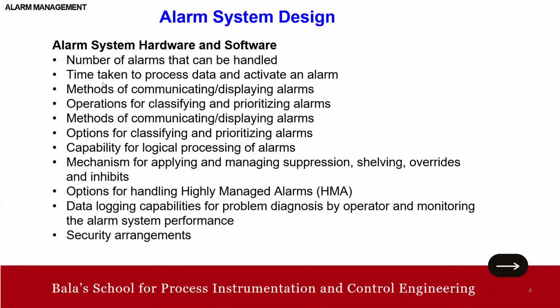So number of alarms, time taken to process data and activate an alarm, method of communicating and displaying alarm, option for classifying and prioritizing the alarm, capability for logical processing of alarm, mechanism for applying and managing suppression, options for handling highly managed alarm, and data logging capabilities and security arrangements. Okay, right. So this is about the alarm system hardware.